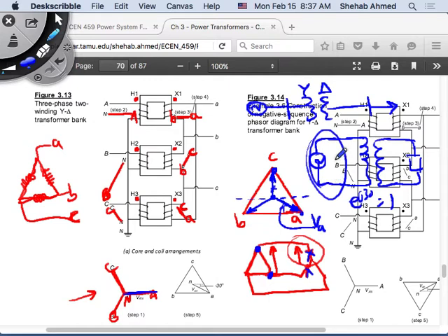It goes to the transformer. The transformer secondary side is phase shifting the input, right? It has phase shifted the input with respect to the output now. The output, where? The output as a single phase equivalent star of the delta secondary of the transformer. Confusing, right? So here, the transformer secondary side is a delta.